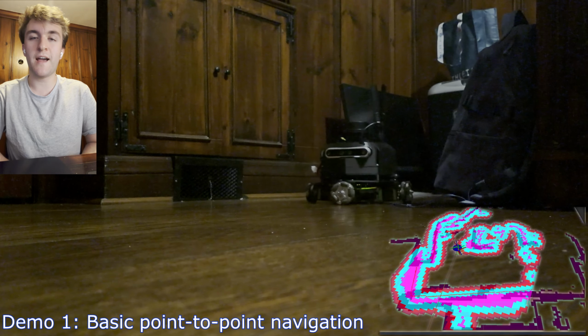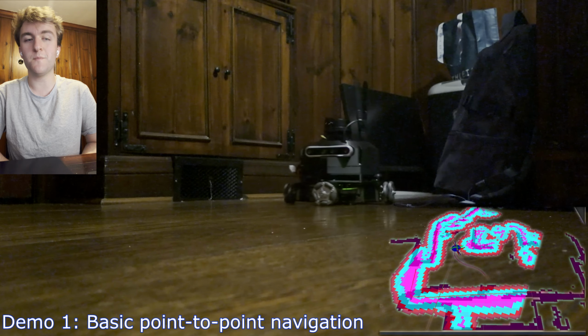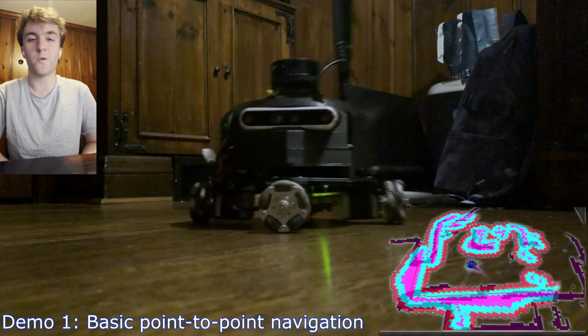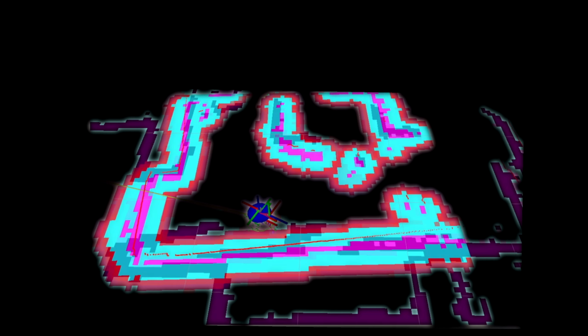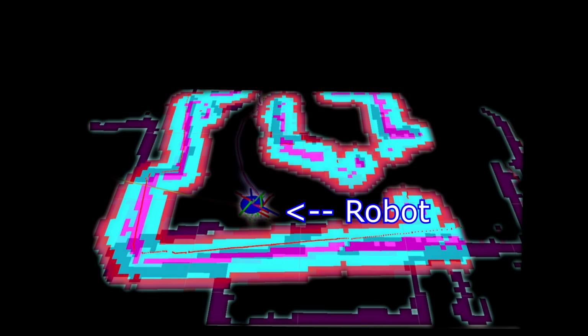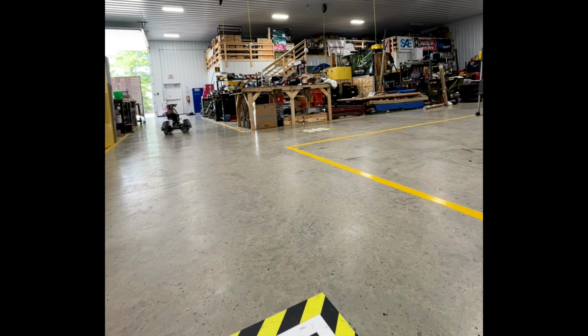The motor controller, CAD, and navigation setup are all fully custom. You can see the robot effortlessly going through its environment in the path planner in the bottom right. The Nav2 library uses a pre-scan map of the environment to find an optimal path for your robot, considering global optimality and also local behaviors such as speed and path adherence. It does this by merging an obstacle layer resulting from the robot's LiDAR scans with a pre-scanned static layer and inflating a danger zone around any obstacles.